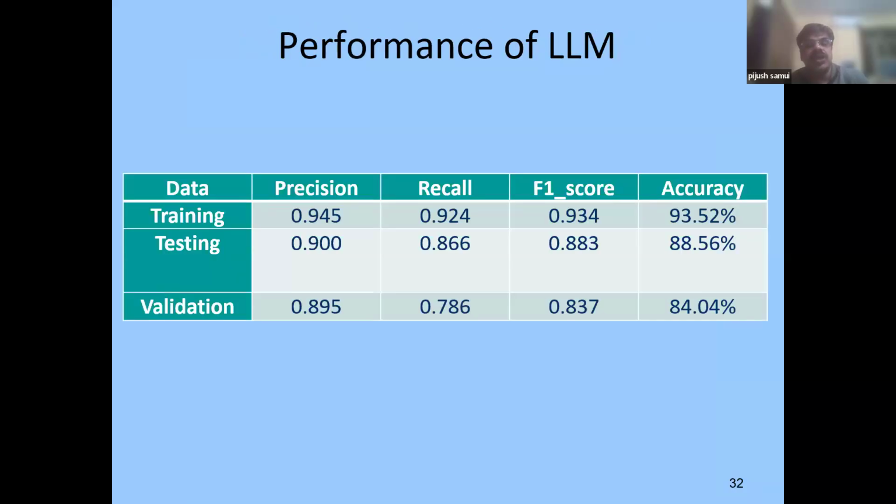If you calculate the accuracy, the testing accuracy has been reduced by almost 6% because we are using fewer parameters. That means if you use fewer parameters, the model does not give a good result. So it is better to use many more parameters, just like we did in the first model, where testing accuracy came around 88.56 percent. I tried to get a better result, but in actual case it did not happen. So you have to use many parameters to determine the liquefaction potential of the soil.